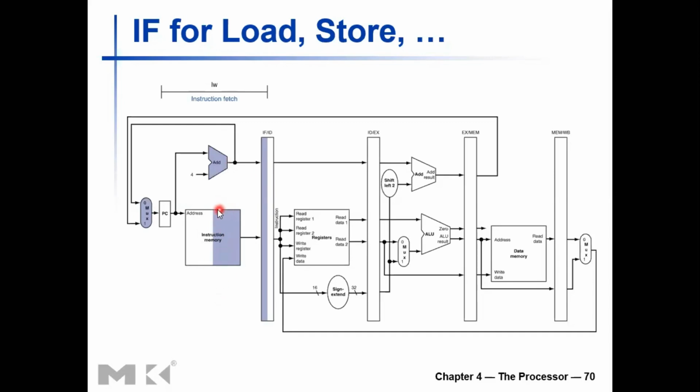So we shade the right-hand side to indicate the reading of this device, and in the pipeline register, we are writing to this register in this clock cycle, or at the end of this clock cycle, which actually happens after the start of the next clock cycle.